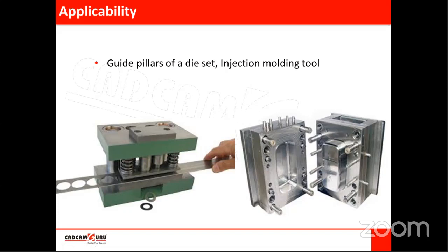So again, alignment is important here. For ejecting the component, we have to disassemble this mold, means these two parts get separated. Core and cavity will get separated, and the component will be ejected, generally by ejector pins.